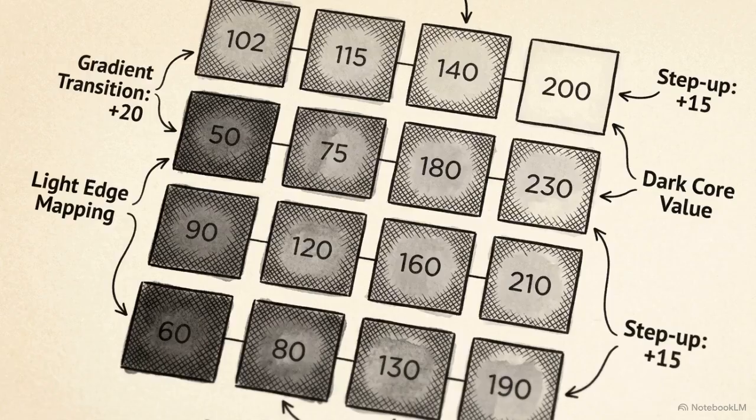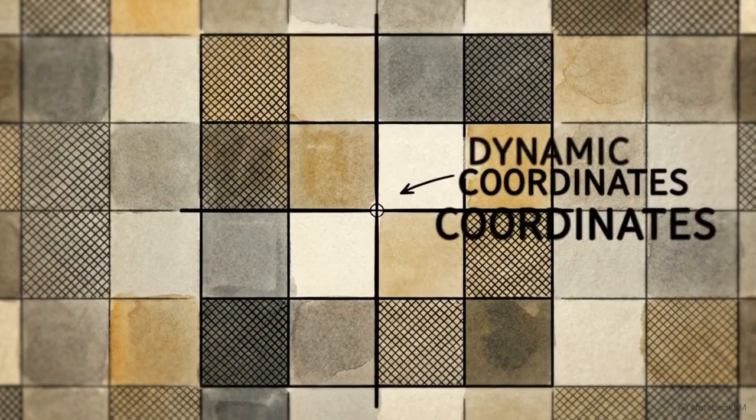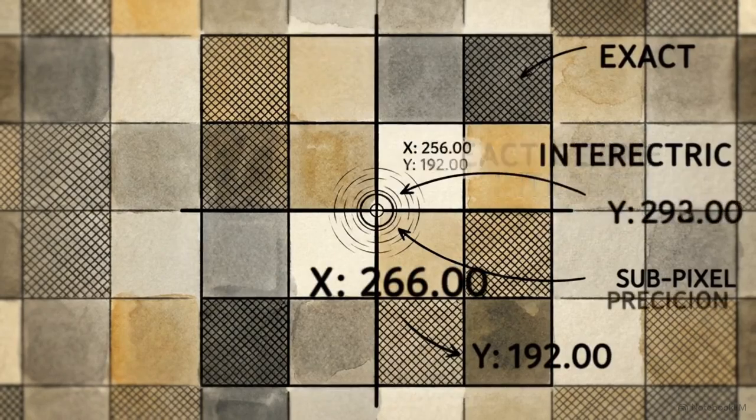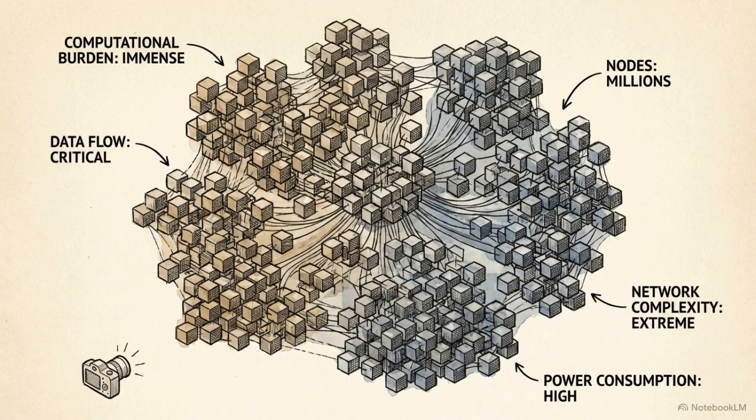To solve this, processing software analyzes the grayscale values of adjacent pixels. By calculating the gradients between them, the algorithm establishes subpixel coordinates, snapping to intersections with an accuracy of up to 0.3 pixels. DLT shifts the burden of accuracy away from the camera's physical optics. It places the workload entirely onto heavy computational mapping of the image against known control points.